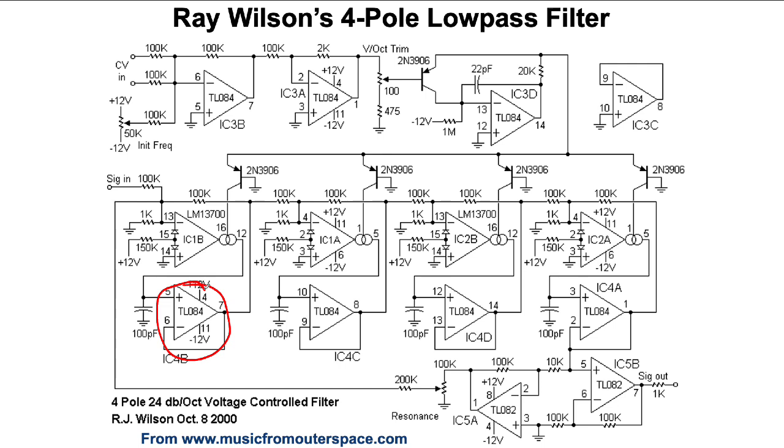They might not have had access to JFET input op amps like we have nowadays that have high impedance inputs. If we follow the output of the 4th filter, we see that it winds up here, it gets buffered. Okay, this is a little confusing because of the way ground is written here. It makes you think that this op amp and this op amp are somehow related more than they are. If I was drawing this, I would probably put the ground here, and I would probably put a ground here and separate this to try to make that clear.